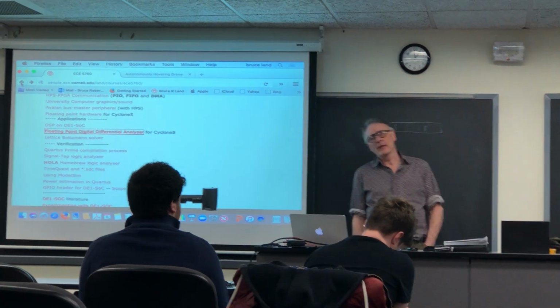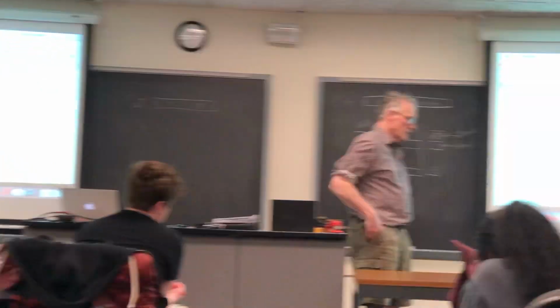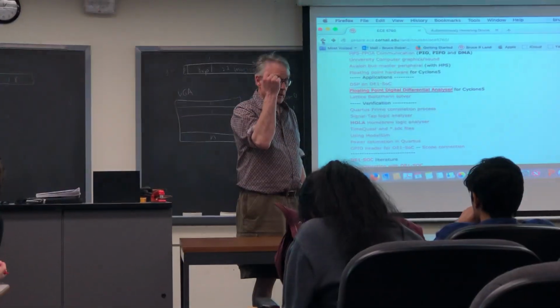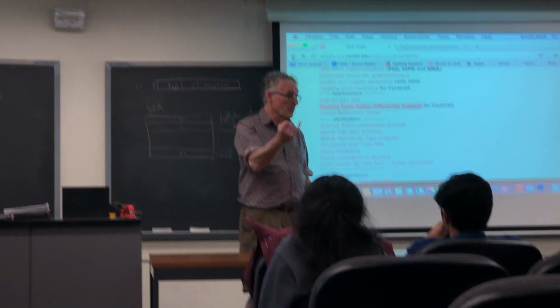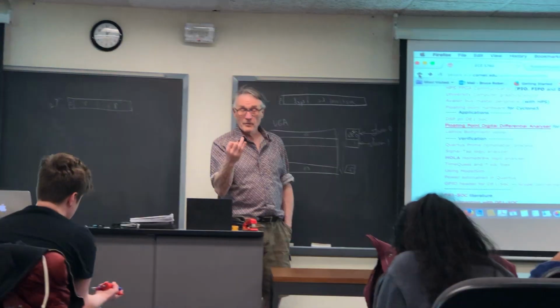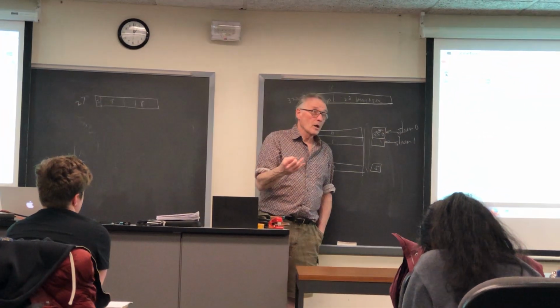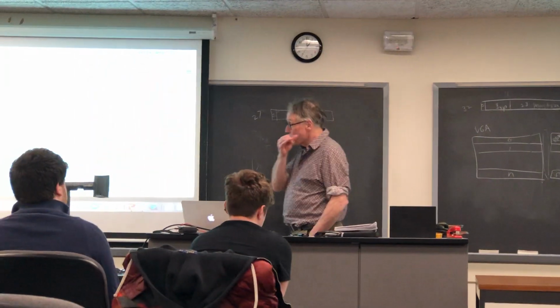So there's a lot to think about for lab 3, because that makes life interesting. How are you going to optimize the pipeline? Are you going to make it a serial pipeline with 1 multiplier? Are you gonna use 3 multipliers and make it a parallel pipeline? How many pipelines can you fit on the FPGA?